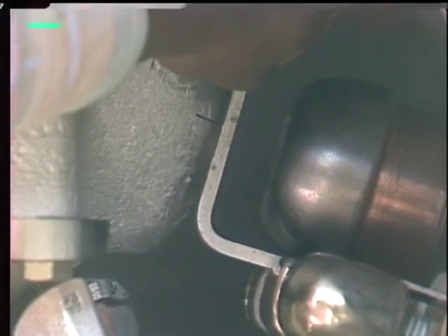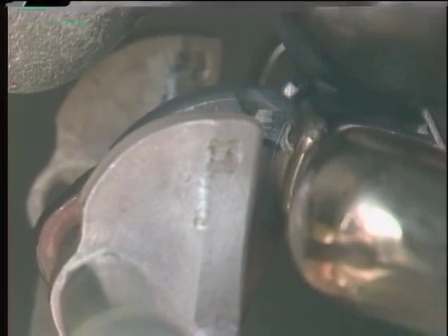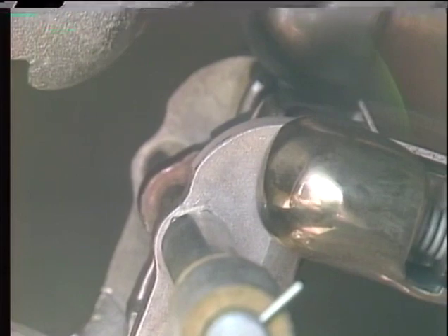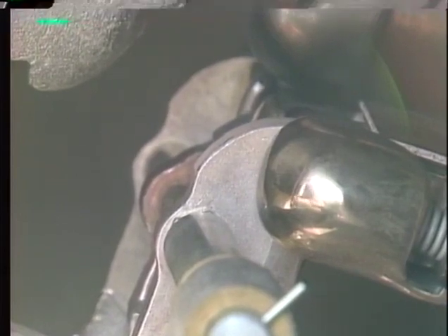The space between each arcing ring and stationary contact is also checked. Here the check is made using an L-shaped gauge. If the spacing is not within an acceptable tolerance, the contact may need to be adjusted. Then, as with other breakers, the contacts are partially closed to check initial contact engagement and alignment. Then the contacts are closed the rest of the way to check contact wipe.